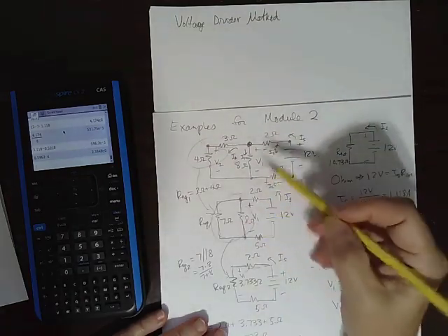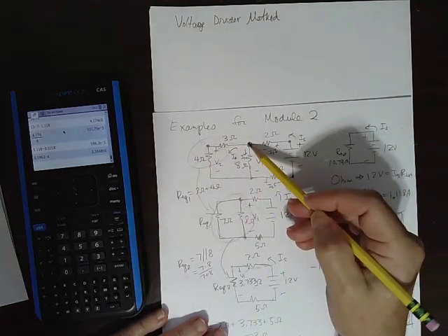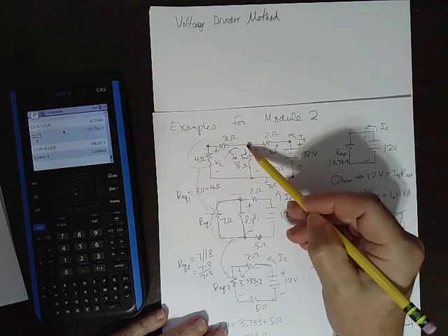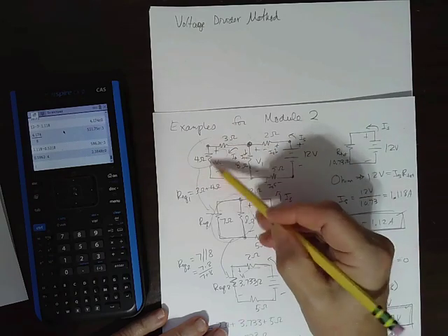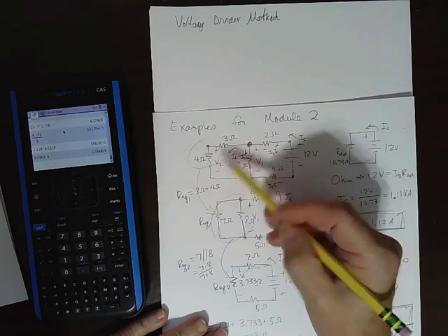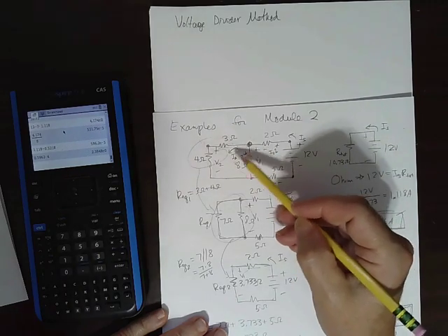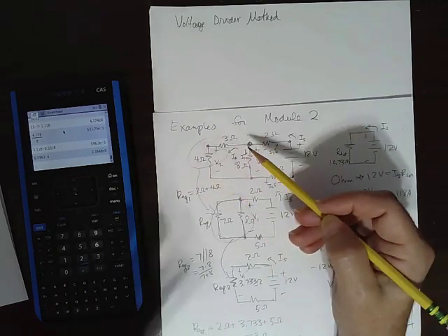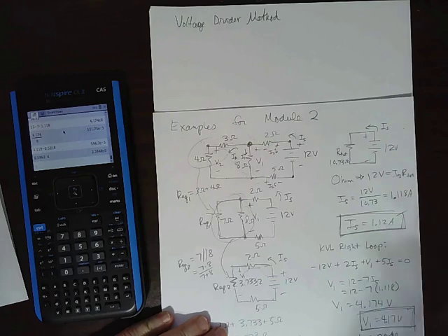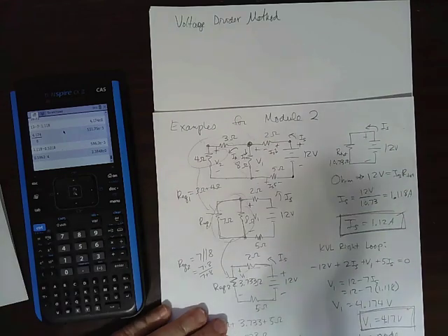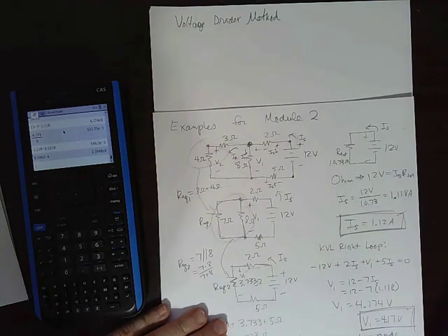And then if we look at this circuit, if we know V1, we know the voltage across these 2 resistors, so we can use a voltage divider. Since they're just series resistors, no other things in there, we can use that to get V2, the voltage of any one of those 2.